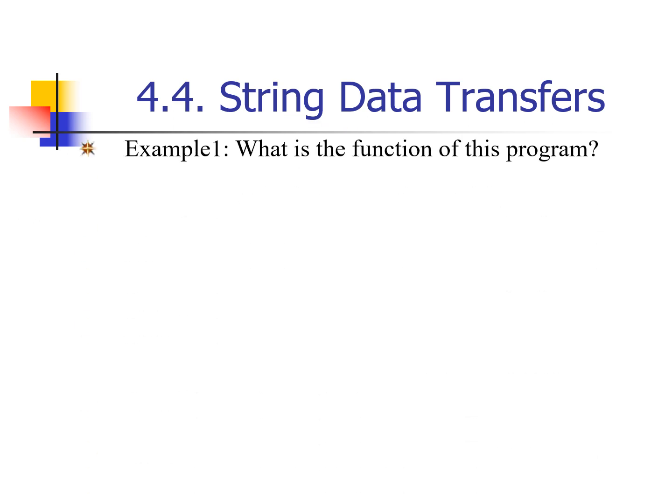Again, it's better explained by an example. And here is a program. Good. What does this instruction do? Well, you have a block of data named list1. You will take the least significant 16 bits from your list1, place them into DI, and the most significant 16 bits into your ES.